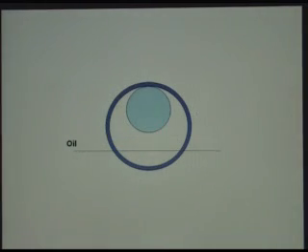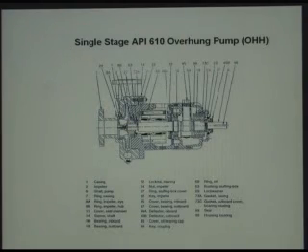The way that the bearings are lubricated, like I said, there's a dipping ring lubrication system. As the shaft spins, there's a larger ring that's just sitting on top of the shaft, and this ring also rotates. It rotates down into the oil reservoir at the bottom of the bearing housing, which picks up oil from viscosity, brings it up and deposits it on top of the shaft. And then from there, it moves along the shaft and goes out to the bearings and lubricates the bearings. It's a nice little system, very reliable. Not a whole lot that can go wrong with something like that.